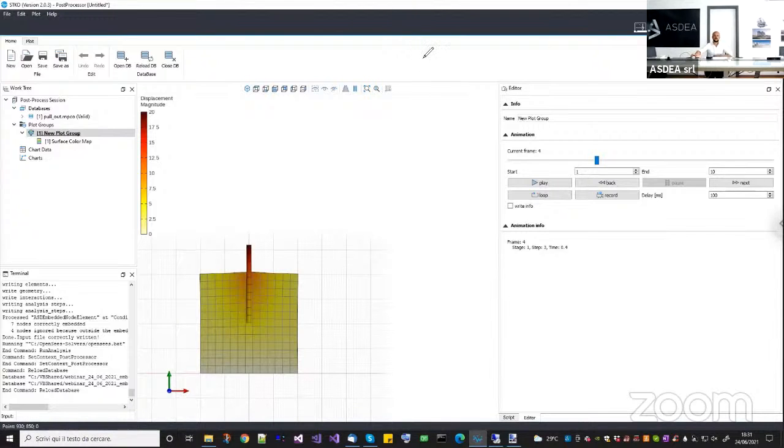Here. Okay. As I said before to Dennis, for example, if a node falls inside, like in this case, it is the weighted average of all the three nodes. But if another node falls in the middle of an edge, it will be the weighted average of this edge. So for example, if my edge moves like this, so this node goes down, this node goes up, then my node will move here. So it will be forced to remain on the edge.